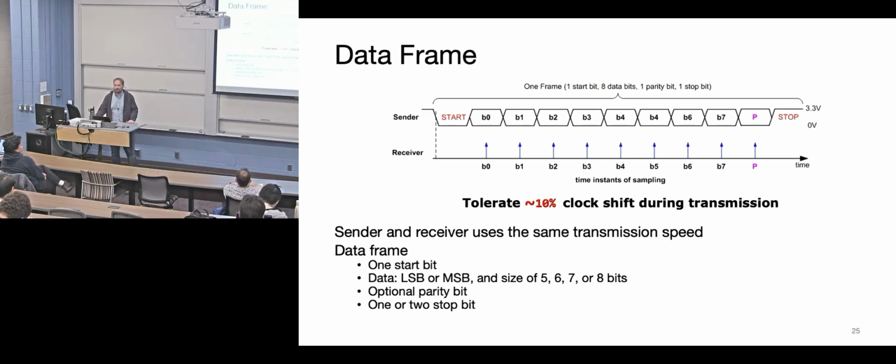So does that help check if your clock shift is too much? It could be the clock shift is too much, but it could be external noise came in, right? There could be lots of reasons, because this protocol was originally developed to go across a room or across a building. It's more important, probably not on a PCB, but going from a PCB to something else, 2 different devices. Would you just request a new packet if the parity bit is wrong? Yep. Or throw an error to the user or something. It's good to at least know that your packet's been corrupted.